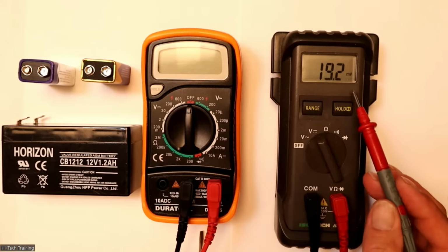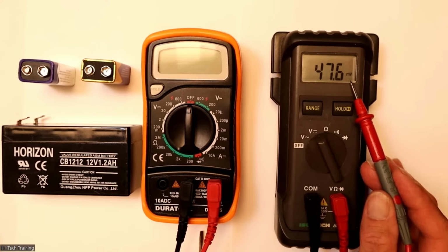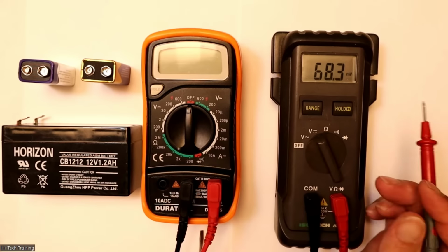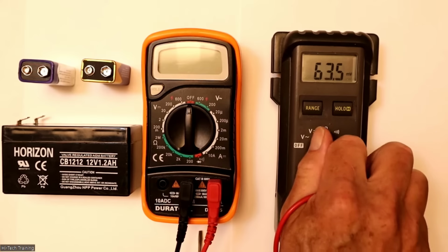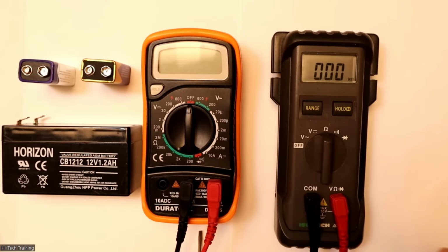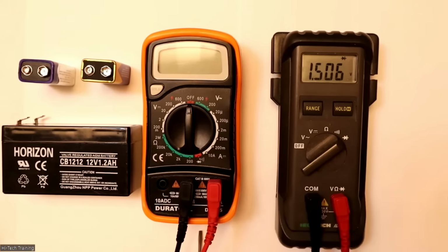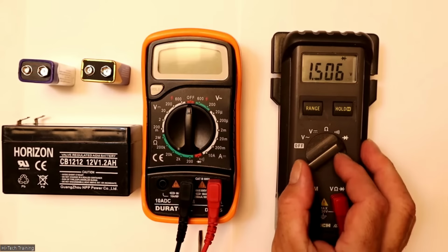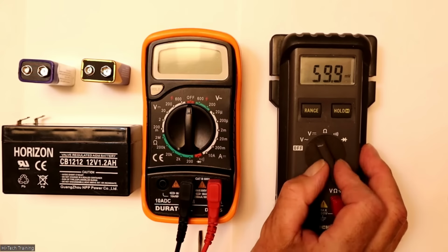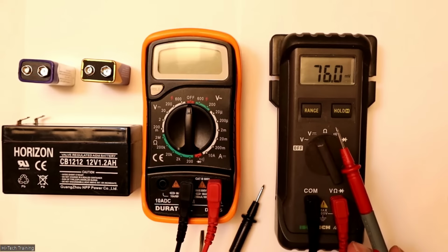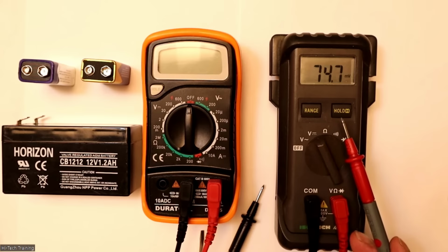I'm picking up mV, millivolts, which is a small voltage reading at present here. Literally from the air, I'm not connected onto anything with these probes. Measure ohms, resistance as well. And there's also a continuity tester and a diode tester over here. So this can do lots of things, but I like this meter because if you want to measure, say, DC volts, all you do is you go into DC volts and it will pick the range for you. It's a bit like a car with an automatic transmission that it'll select the gear automatically for you.